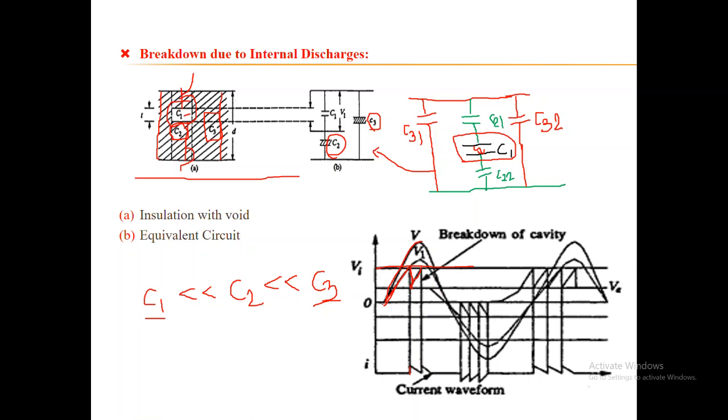Okay, so when the supply voltage becomes lower than the voltage across the capacitor, no discharge is observed, because from the peak magnitude during the positive half cycle, the wave is now moving towards the negative side. After some period of time, the supply voltage magnitude becomes lower than the voltage across the capacitor. In that stage the capacitor will not fully charge.